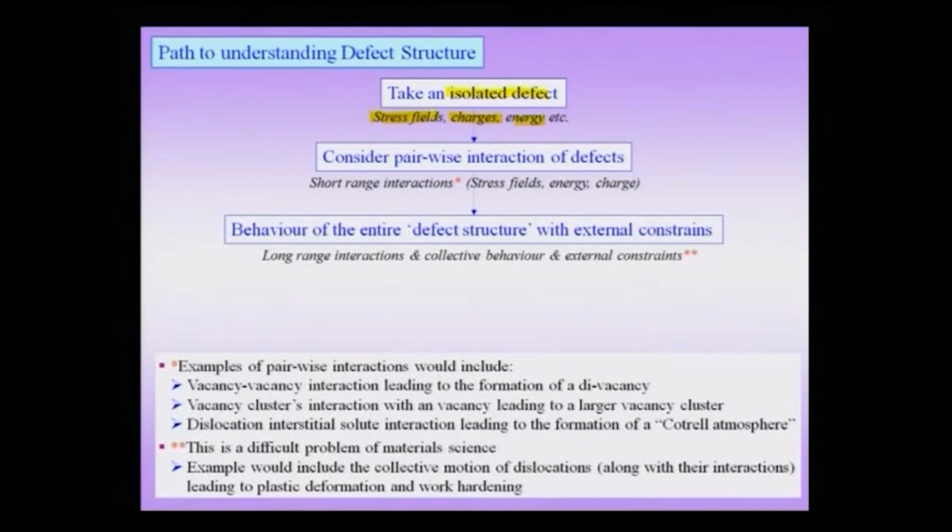If this defect is going to cost the crystal energy, then such a defect could be in a metastable state, and when you anneal the crystal, the defect is going to leave the crystal. In other words, this energy associated with the defect is going to dictate if it is stable or metastable, and how much energy is associated at the core of the defect and also around it.